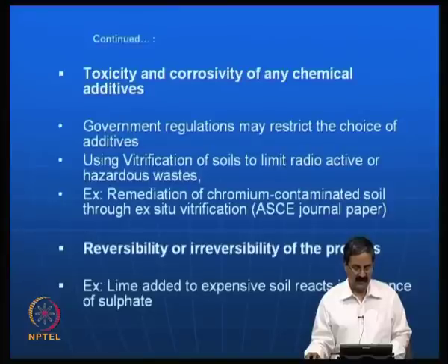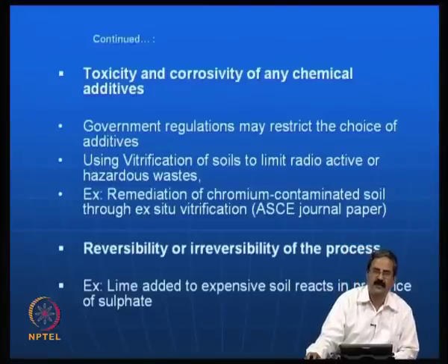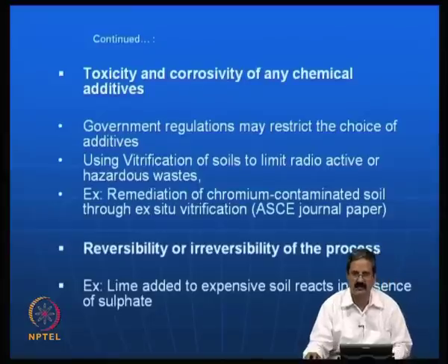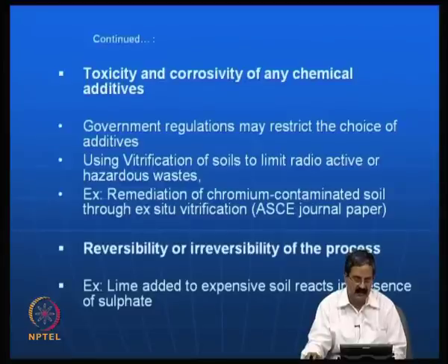Another important point that governs the choice of ground improvement technique is the reversibility or the irreversibility of the process. Actually, people have been using lime for expansive soil treatment. What we hope here is that the soil will not swell when you add lime, that is our assumption. But you have seen that particularly when sulphate is present in the soil, the expansive soil nature comes back, and the heave will be more than you expect. Say for example, the percent heave may be 5% in one case or 10%. When the sulphate soil is present, it is so bad that whatever stabilization you have done becomes useless.